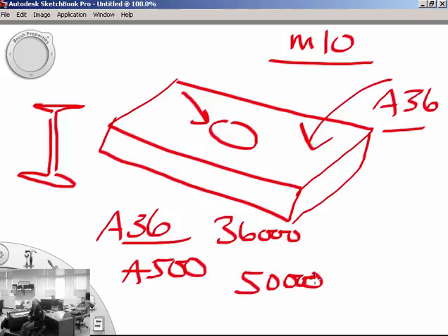Now, that is typically the case. Most of our steel in our large buildings, we're using A500 as kind of the standard. Don't get me wrong, though, we still use A36 in some stuff. But the designers have to be very much aware of it because that's a significant strength difference, right? Now, surprisingly, the ductility, how much it deflects, doesn't shift that much. But this is your ultimate failure value. This is where this thing actually starts to break apart and things go bad.